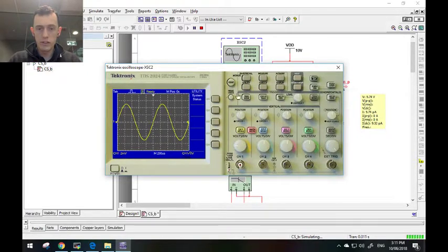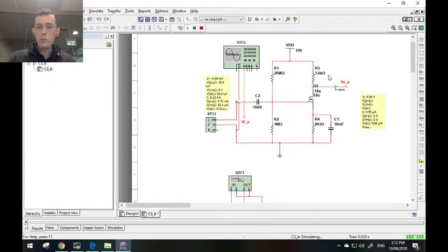Now we'll go utility. Oh, sorry, measure. Channel 1, type, frequency, period, mean. That means around 0, fine. Peak to peak, 10 millivolts. So that's exactly what we want, at 10 millivolts.